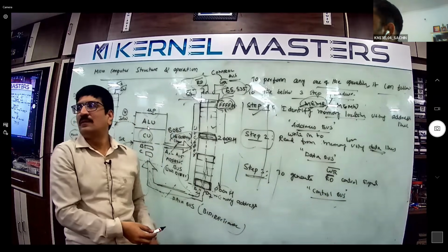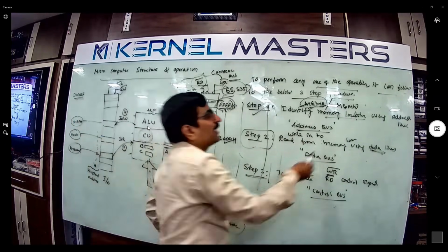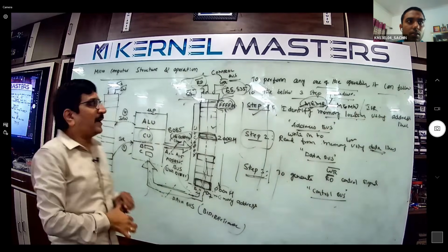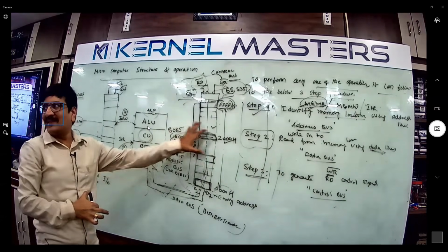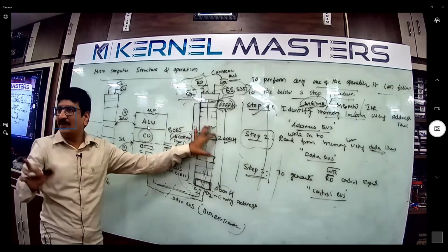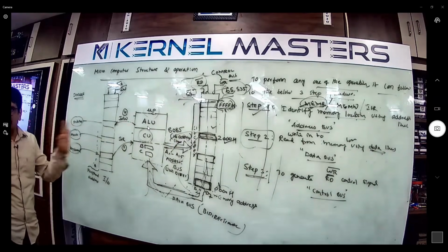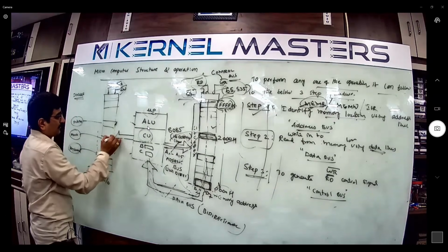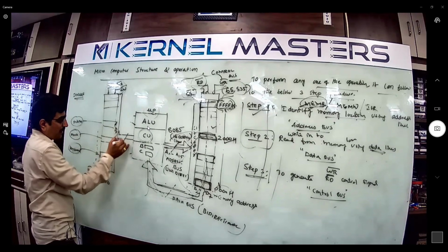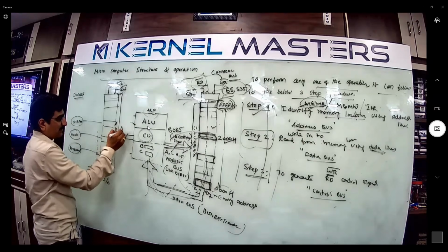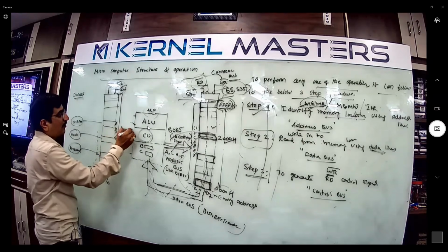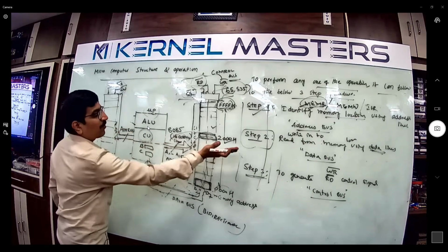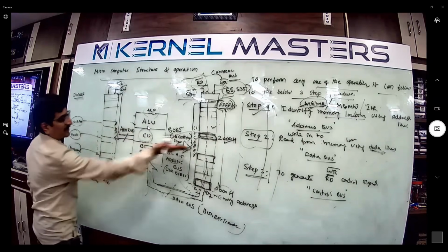So what about IO read? I already told you the way the microprocessor communicates with the memory. It is the same way to communicate with IO, no difference here. Here also there is a decoder and an address bus. The IO address bus and the memory address bus are two different roads actually.